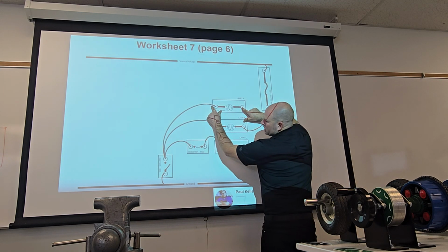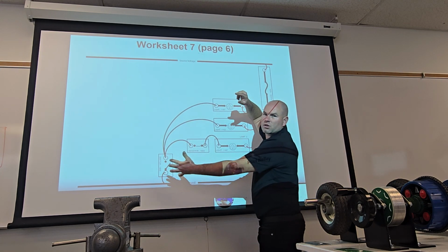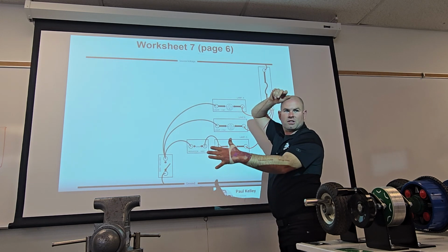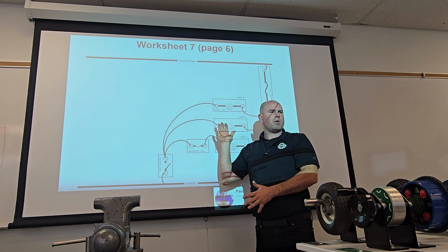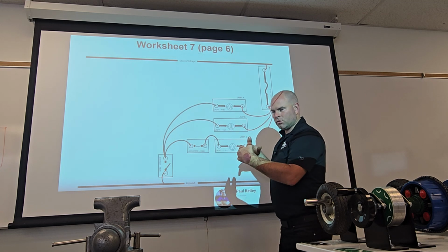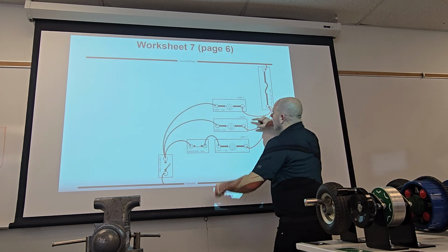Right here, look at what this is. By the way, close the switch, okay? I need to make sure you understand. When we're testing the circuit, you don't test brake lights with the brake switch not pressed. You know that, right? So you'd assume here we'd close this.